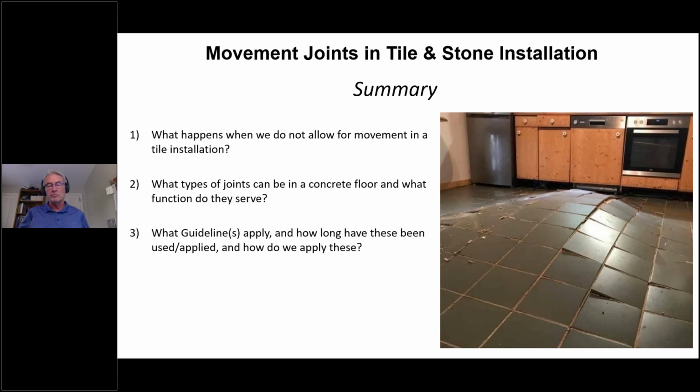But the sealant, you're going to end up having to wait for that to cure way before you're going to be able to put the grout in. Let me just be clear, Jim. You're not saying grout the actual movement joint area. You're saying the walls can be grouted, but you have to leave that area completely open, and you can come back later to put the caulking in there. The field can be grouted, but the perimeter and the movement joint areas have to be left open and clean.